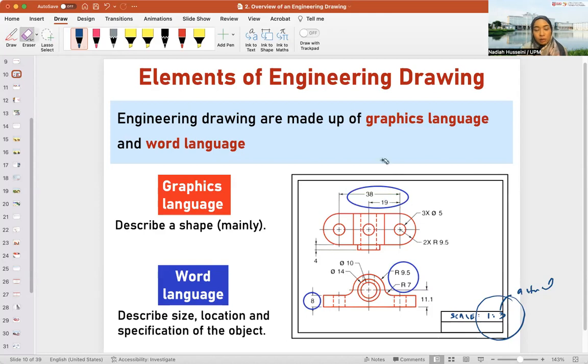Dalam gambar ni, kalau korang pakai ruler, it's not actually 38. Dia 38 bahagi 3 dalam gambar. Tapi kita letak actual. This is the actual number. Drawing sahaja yang ikut scale. Okay, I'm going to repeat myself here. When you have a scale that is not 1 to 1, dia 1 to 3 ke, 2 to 1 ke, whatever, the drawing is according to scale, but the dimension labeled is always the actual dimension.